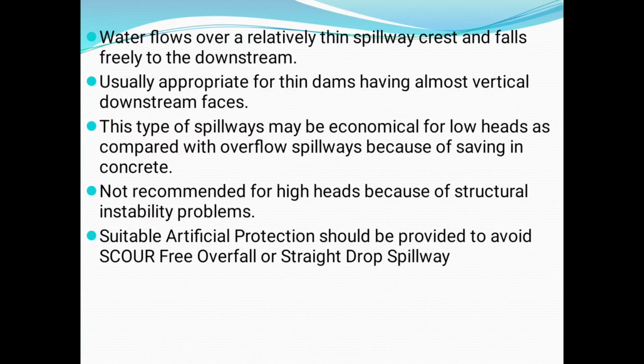Free overflow or straight drop spillway: water flows over a relatively thin spillway crest and falls freely to the downstream. Usually appropriate for thin dams having almost vertical downstream faces. This type of spillway may be economical for low head as compared with the overflow spillway because of saving in concrete. Not recommended for high head because of structural instability problems. Suitable artificial protection should be provided to avoid scour.